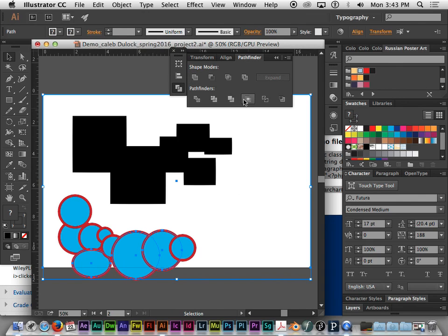And what I'll do is we can use things like crop to cut off the edge so that it slices off anything that goes outside the upper layer rectangle. We could use divide if we wanted to. The problem with divide is that if you do that, then it suddenly adds a stroke line that goes across the base border of the shapes. So you get funny options that can sometimes occur when your shapes have other appearance options like stroke turned on. But it's a quick way to cut off outside edge areas that you don't want visible. And it allows you to do it in a way that's a clean cut.